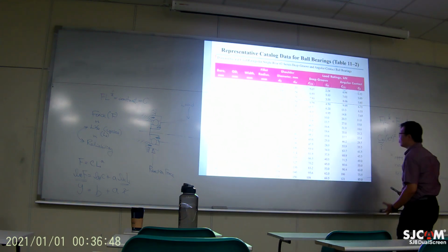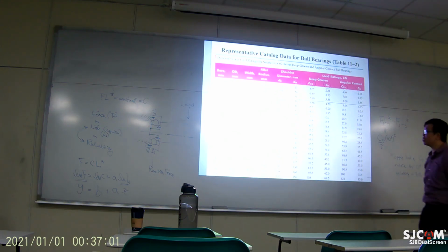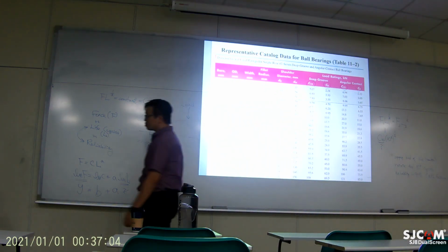So from this catalog, depending on how you expect this bearing to last its life, you then know the allowable force that should be applied to the bearing.